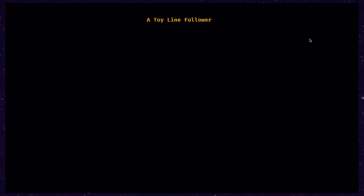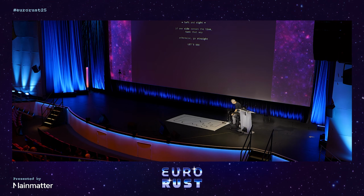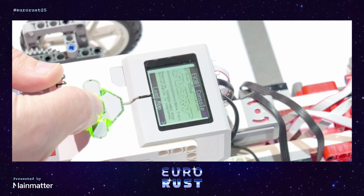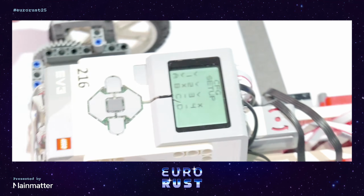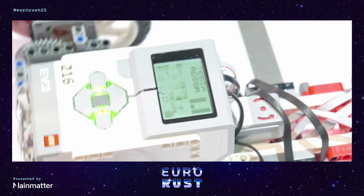First, let's try thinking about a toy line follower. We start with something simple. The idea is that we only use two sensors, left and right. If one side senses the line, go that way, because otherwise you would go out. Otherwise, go straight. And that's it. So let's start this thing up. Software doing controls, motor starting. Everything is supposed to be working.